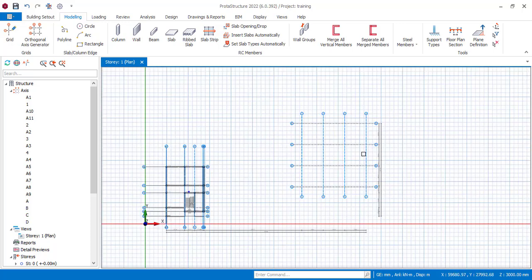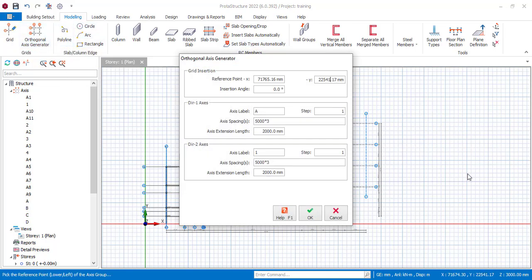Now let's say I don't want this, or I just want to take another orthogonal axis and play around with it. I will click anywhere around my window. In this case, I'm going to show you that you can use a comma, 4 meters, comma, 3 meters, because in most cases you will most likely not have equal spans. So in that case you can use the comma.